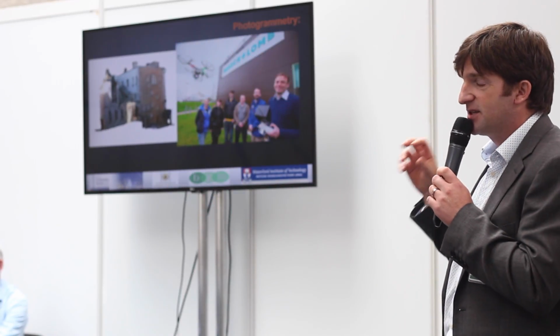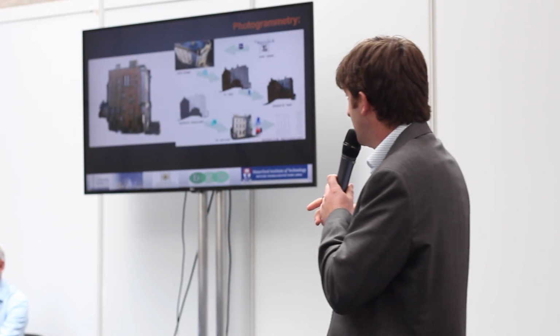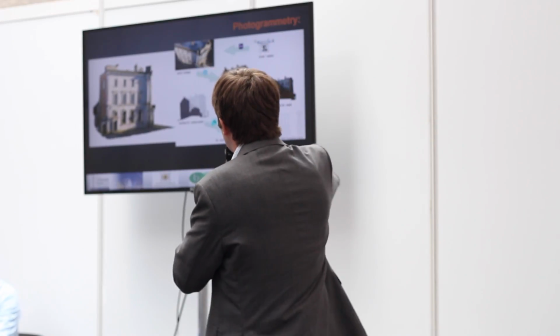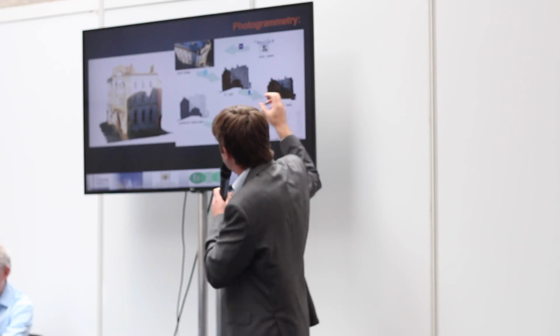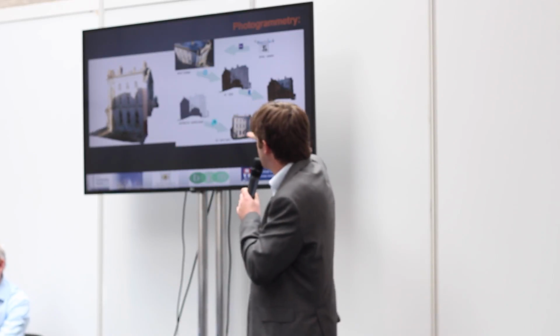Yes, as you can see from the model, it needed some tweaks. That portico is not actually a Gaudi building, so it needed to be tweaked when we got it back in, but 90% of the data was captured using the drone data. And then we're able to take our aerial footage back to a 3D mesh, into textured meshes, rectified surface meshes, and then into a 3D point cloud. That then can be brought back into Revit, and we've got an active model.